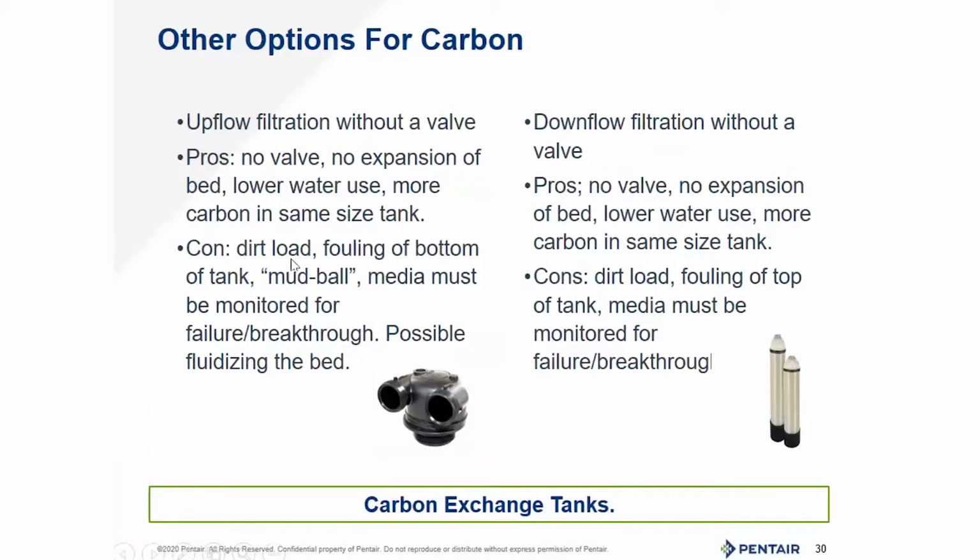And the cons of that are dirt load. You're going to get a fouling at the bottom of the tank and a mud ball that's going to be difficult to get water flow through if you have a dirty water scenario. And the media must be monitored for failure or breakthrough. So you're going to either have someone sampling water here or specialized sensors to trigger that say, hey, stop using water. You need to change this tank.